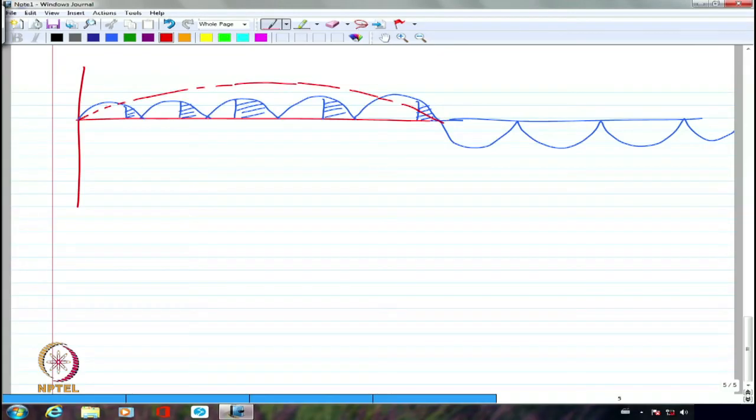So the control for a cycloconverter is not very simple because it is a continuously varying firing angle. I will definitely be varying the firing angle, but if it is an RL load, like a synchronous motor, I will have to take into account that there will be some negative portion of the voltage coming up. That's the reason I told you that for 90 degrees, output is 0, only if it is continuous conduction. So I need to know what kind of load I am connecting to, and accordingly I have to calculate the kind of firing angle I have to give such that my output voltage approximates to a sinusoid.